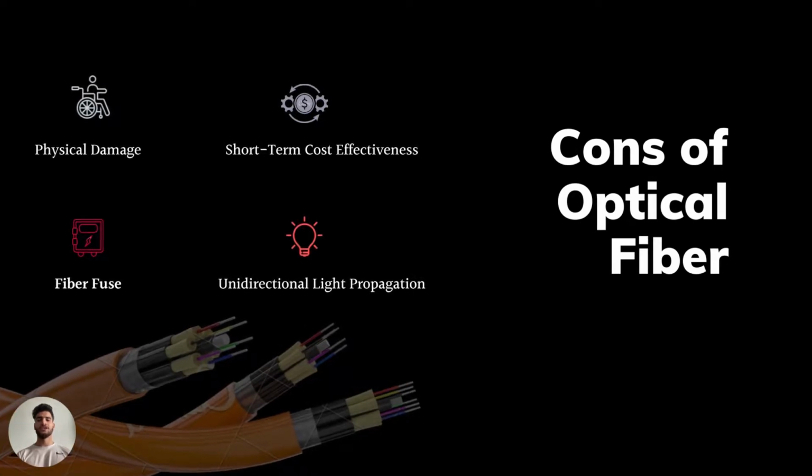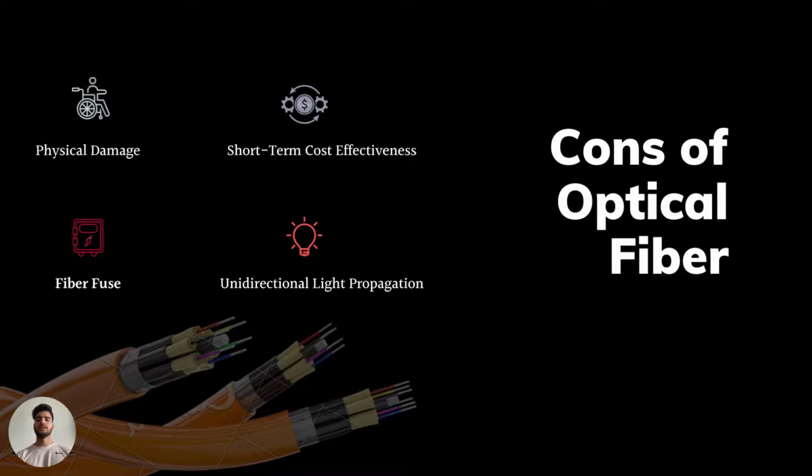Challenges of using optical fiber. Physical damage. Fiber is thinner and lighter than metallic wiring, so it makes for a more delicate system. Because fiber optics are small, they can be easily cut by accident during building renovations or rewiring. As fiber optic cable can transmit much more data than a metallic network, fewer cables serve a greater number of people. This means that cutting just one cable could disrupt service for a large number of businesses and individuals.